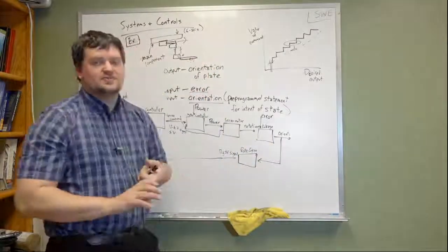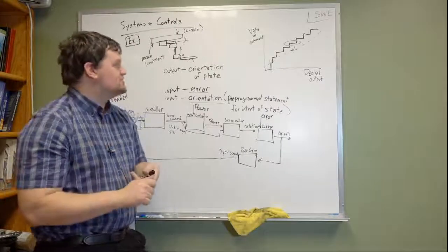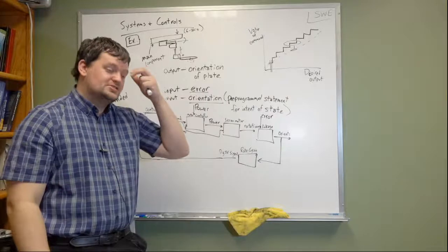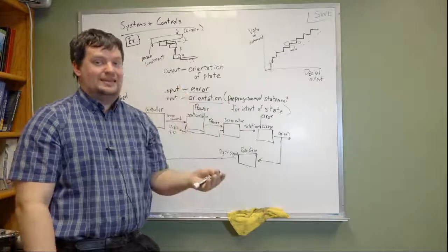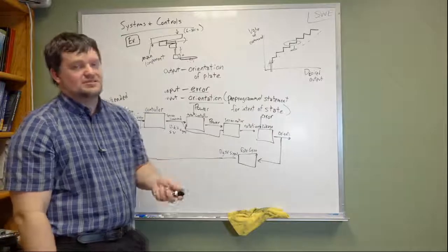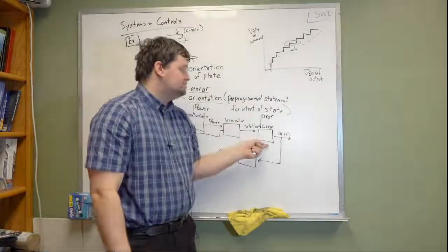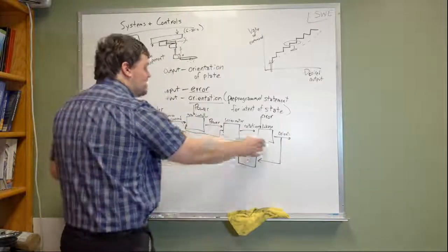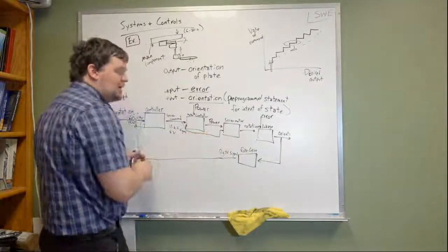Your joints are going to have some flexibility, and your components are going to be flexible. As they handle load, as they handle vibrations, they are going to shake slightly. It's not very much. Again, you're still talking probably in the tens of thousandths, but there is still some error associated here.